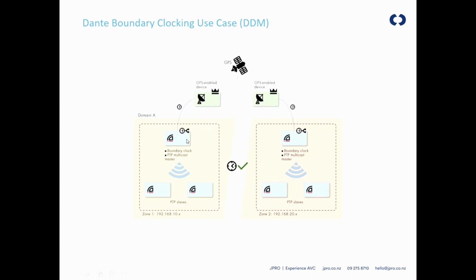And for every boundary clock, it means that it will be able to receive those packets and reclock it out through that new system. So where you might be pushing the restraints of Dante by going above 400 devices, for example, and you start having PTP issues, using boundary clocks and splitting systems into smaller domains, and having them less reliant on that one master device distributing all the master clock out, creates multitudes of submasters that you can use.